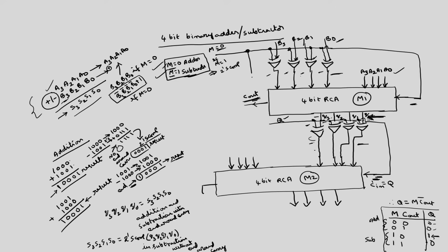This M signal is one input, and C out you take through a NOT gate, and you obtain the result through the AND gate. This output has to be given as Q. This is the Q signal. So, this Q signal will be one input of the 4 exclusive OR gates, and at the same time the C in. Okay. So, this logic will play.